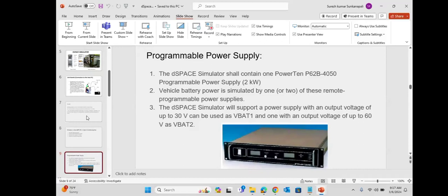And that too, this HIL system can be used by multiple test engineers, right? Due to that, it can be placed in offshore offices or on-site, so mostly it can be accessed through remote only. We can have access to ControlDesk and AutomationDesk. In ControlDesk, we can see all the outputs and inputs, and in AutomationDesk we can upload all the test cases.